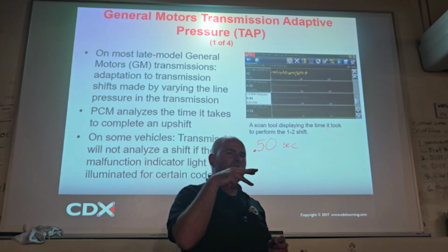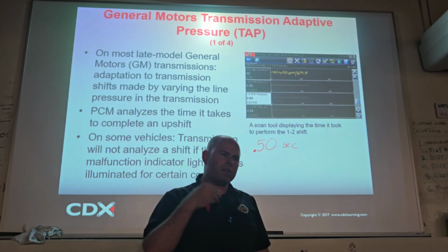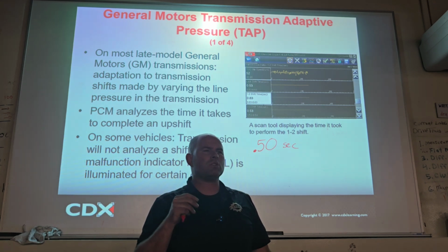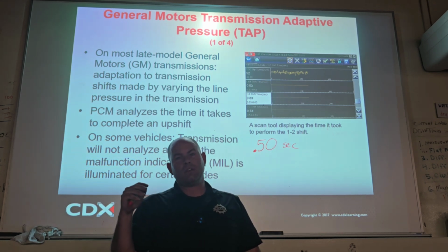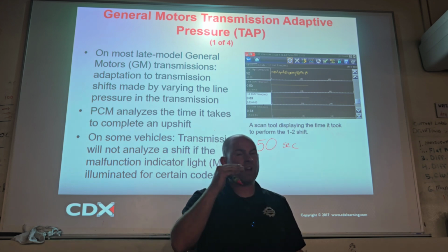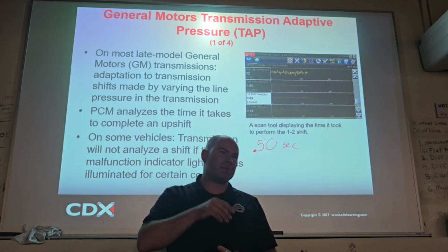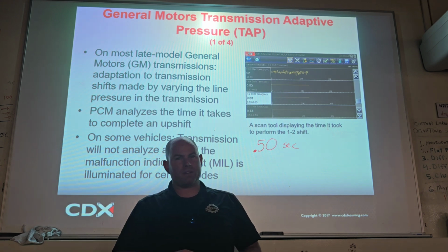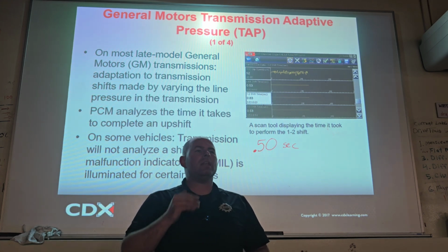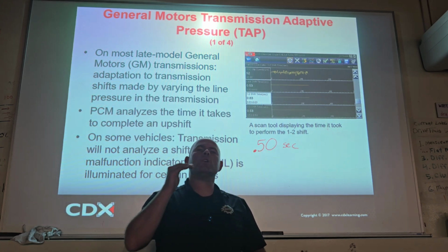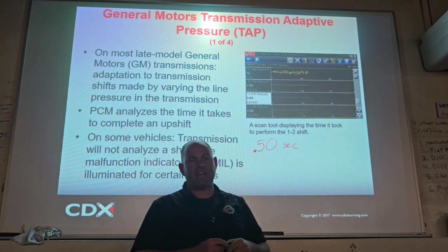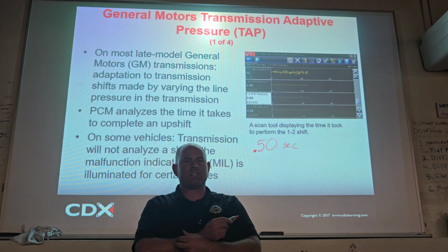Increase, like we take that linear solenoid and say, hey, come on a little quicker. Let's duty cycle that up higher. Rather than doing 50% duty cycle, let's jump right to 60, right? But then as the clutch wears, guess what's going to happen? It's going to jump to 70. And then as the clutch wears more, what's going to happen? 80, 90. By the time it goes to 100, if this time is still over a half a second, you know what it sets?